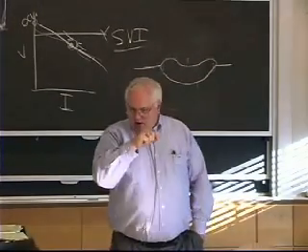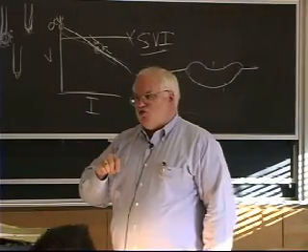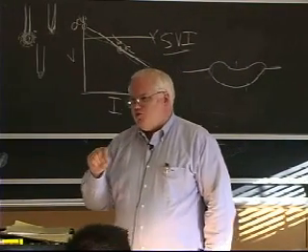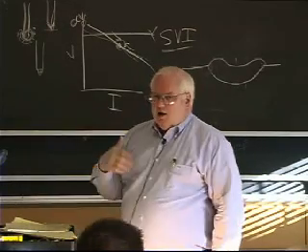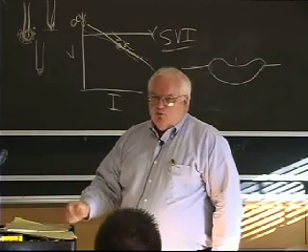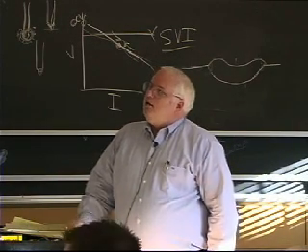Okay, if my combination of travel speed and current and everything is just wrong, I have just the wrong combination, then I'll freeze in an undercut, and that undercut's going to have to be ground out if it's more than about a ½ millimeter deep. Okay. What was the undercut?